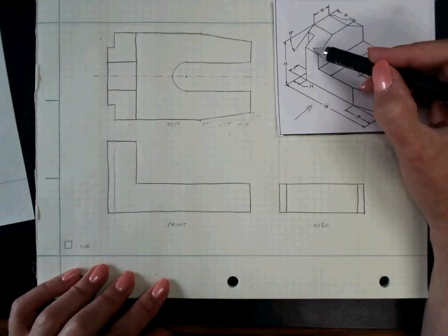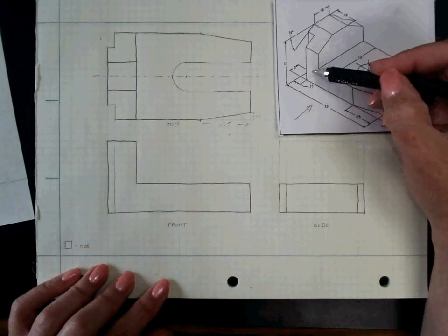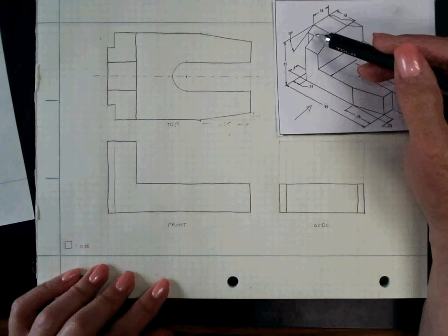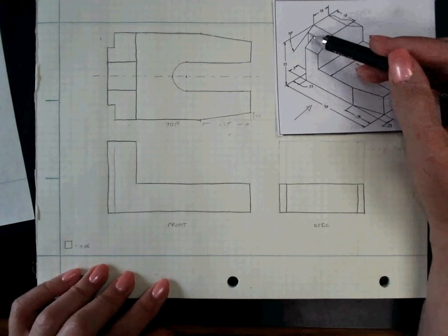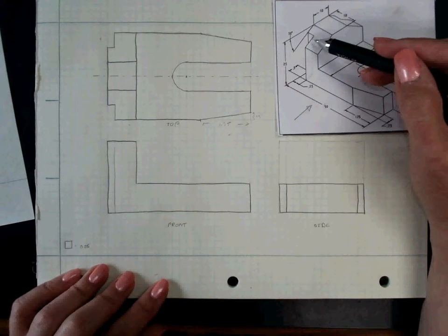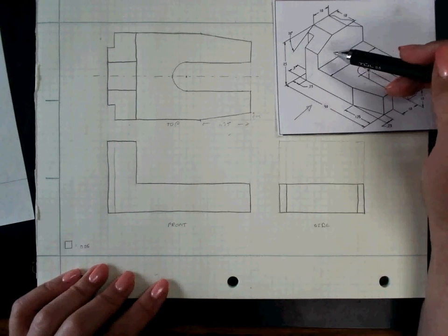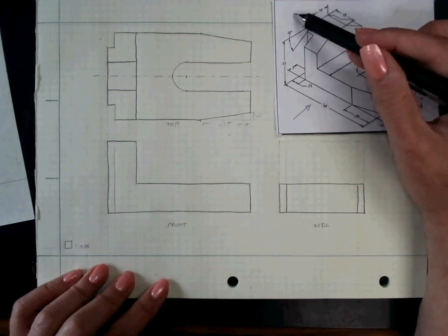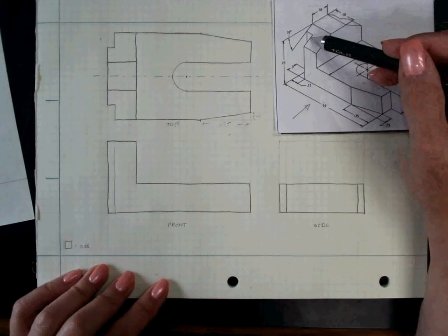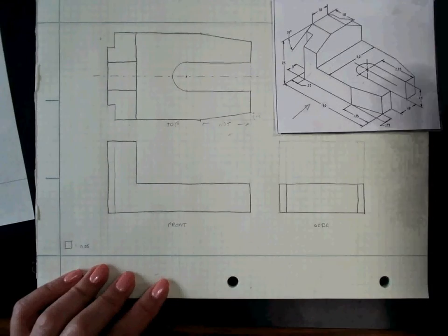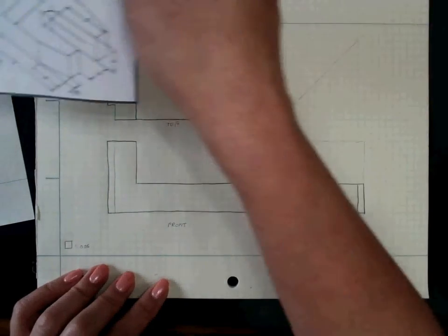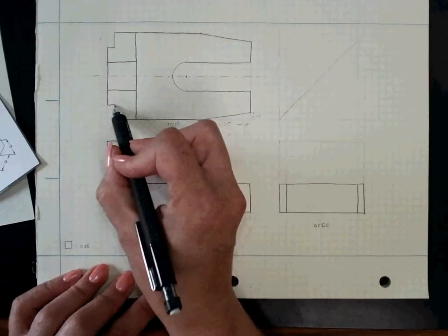Now, this little cutout here that I've dashed in so that I can see it, you might not be able to see on your screen, but that's going to create what we call a hidden edge. A hidden edge is an edge that would exist if I were to draw this object from the opposite view. If I were drawing from the back here, I'd see an edge here. But I don't see that edge on the front, but I need to note that it exists.